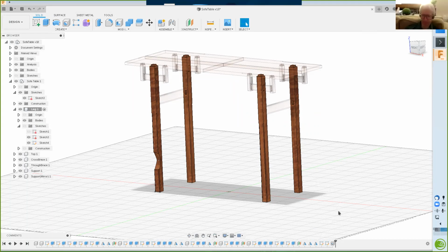Right. So in some CAD packages, you would define each component, like the leg, independently, and then assemble them into this assembly. And then when you use more of the same leg, any changes you make are automatically going to go to all of them. Then if you want to customize one, it's a little bit more involved. And these intricacies of timeline and parent-child relationships frustrate some people because it is more complicated. It is more to learn, but it's part of the power as well.